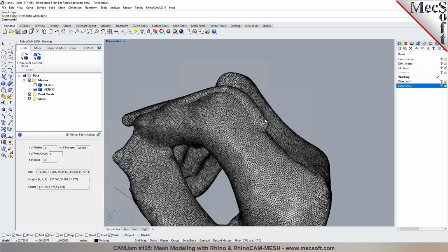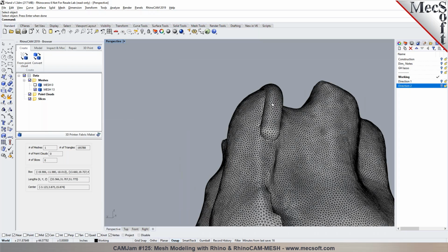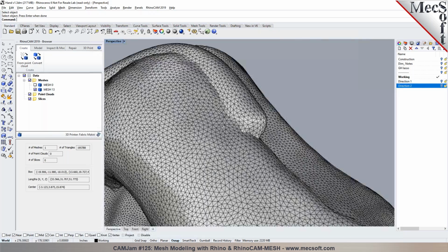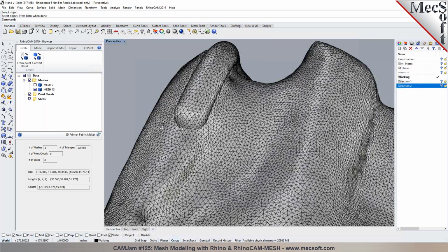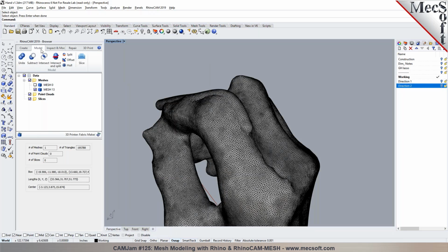So you can see how we were able to take a NURBS, convert it into even a polysurface, and then blend it in. You could have drawn a bunch of curves in here. Absolutely, we could clean that up, no problem. It might just be my OCD, but it looks so much better when all the triangles are about the same size. It makes it much more uniform as you see it right there. Especially if you're going to print it. Although I have a printer, I'm not using it that much for that. What else can you do? What else do I need to know here?